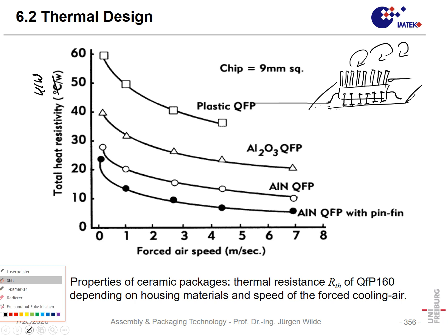Plastic, that's typically a molding compound. And when we just have the device with a certain power, we have a temperature increase of 60 degrees per watt.